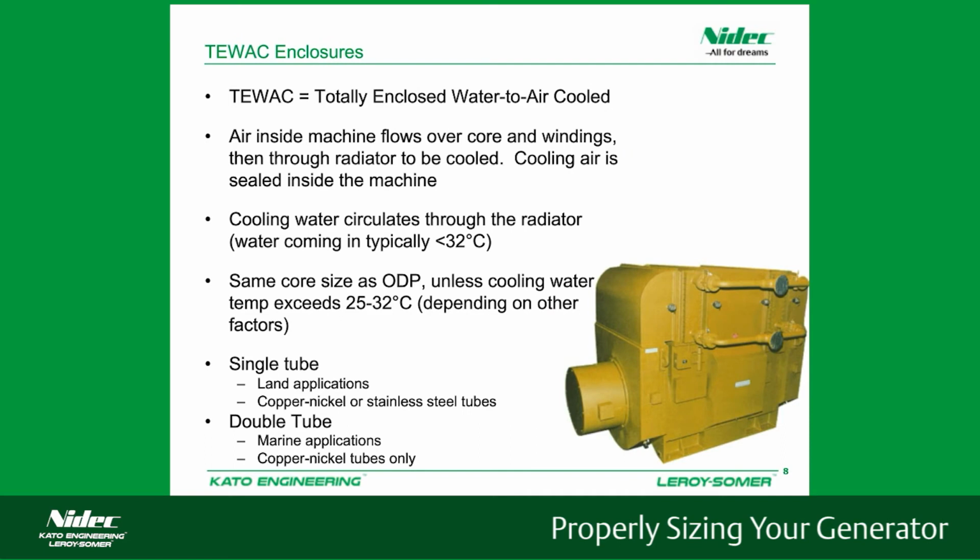Our TWAC is our totally enclosed water to air cooled. So we have air inside the machine with an internal fan moving it around, and that air is sealed in. It's never going to escape, ideally. And then we have water ducted in through the top, so that circulating air is pushed across the ducting that we have water flowing through, and that heat from the cooling air transfers into the water and then is pumped out of the machine.